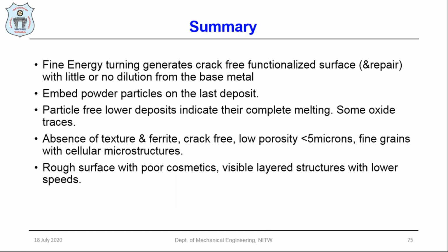The summary of this analysis of the DED technique is that we have to finely tune the energy to obtain crack-free functionalized surfaces, especially for the repair application, with little or no dilution from the base metals. Embedded powder particles and lost deposited particles are because of the highest scanning speeds. The particle-free lower deposition indicates complete melting, and some oxide traces will exist. The absence of texture and ferrite, crack-free, less than 5 microns of porosity, fine grains with a cellular microstructure can be obtained with optimization of the process parameters.